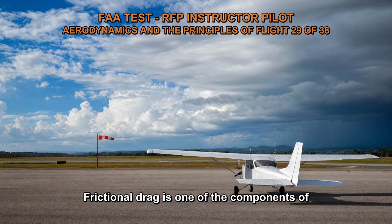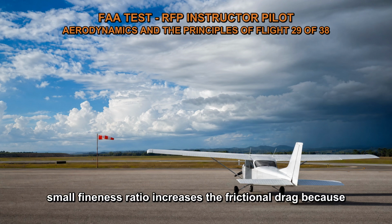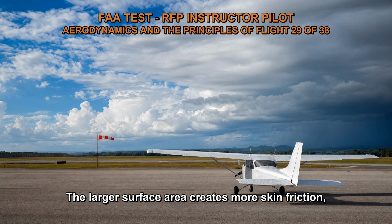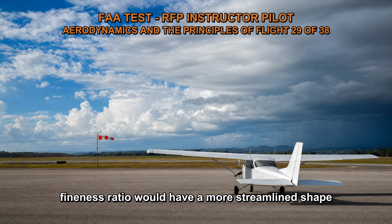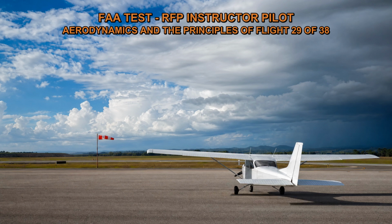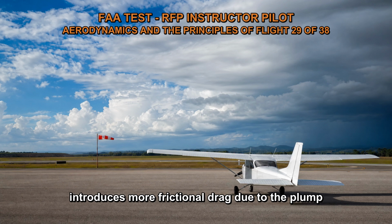Frictional drag is one of the components of total drag and is primarily caused by the shear forces between the air and the surface of the airship. The plump shape of an airship with a small fineness ratio increases the frictional drag because there is more surface area in contact with the airflow. The larger surface area creates more skin friction, which contributes to the overall drag of the airship. In contrast, a sleeker airship with a larger fineness ratio would have a more streamlined shape with reduced surface area exposed to the airflow. This would result in lower frictional drag. Therefore, an airship with a small fineness ratio introduces more frictional drag due to the plump shape of its hull.